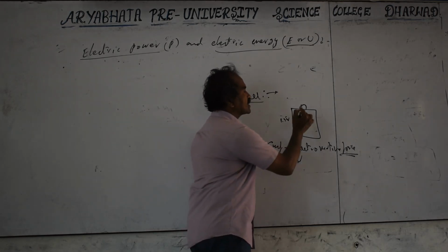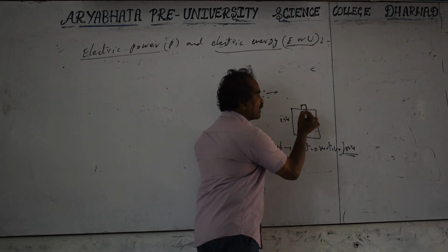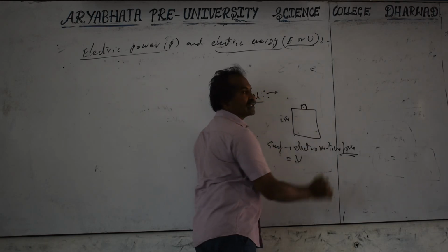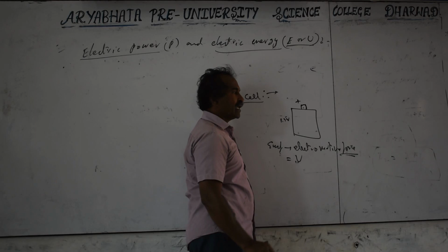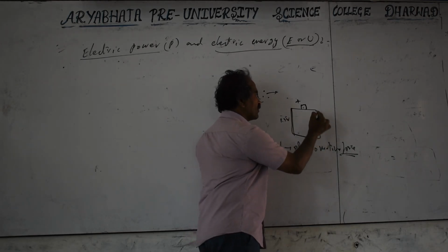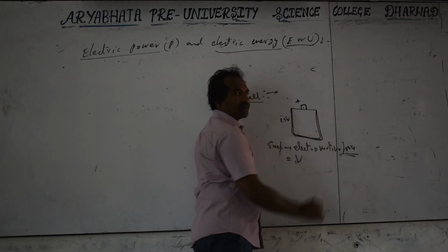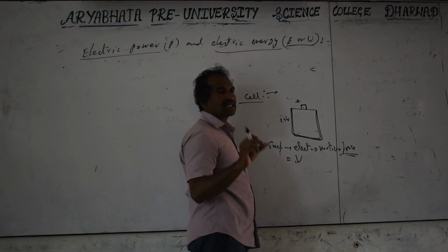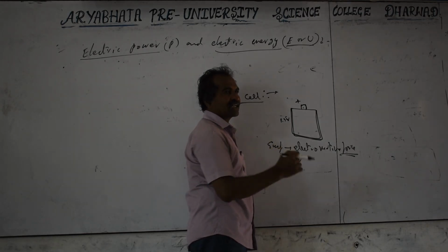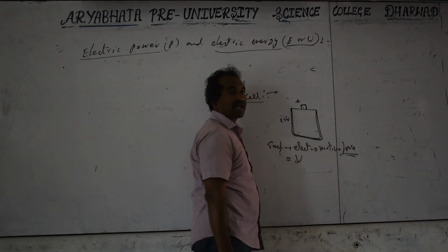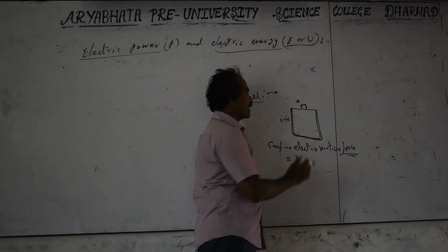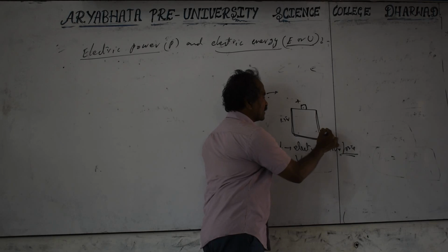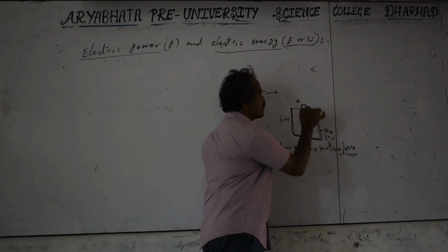You find this tip, maybe metal, but actually inside you find a carbon rod, and it acts like a positive electrode. And zinc will be there. I am talking about the cell we use in the houses. That is not actually dry. Inside it contains ammonium chloride and manganese oxide. A paste will be there inside. And this zinc acts like the negative terminal, plus and minus.